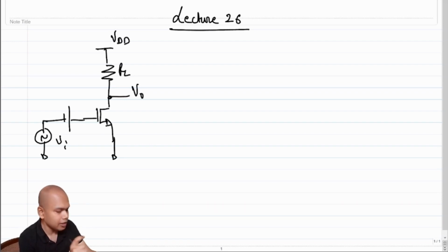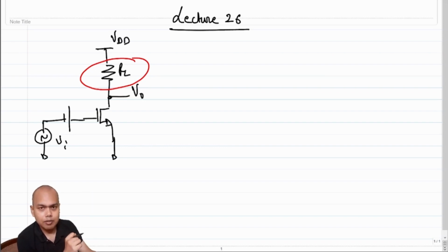The limiting case here is the fact that we have to search for a solution in which the gain is independent of the quiescent drop across the load. So essentially we were trying to figure out, can we replace this guy with something so that the incremental resistance or whatever that thing is independent of the quiescent drop across that thing, right?